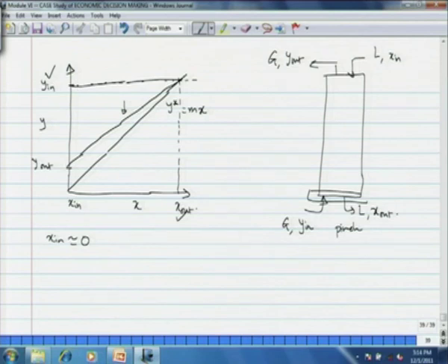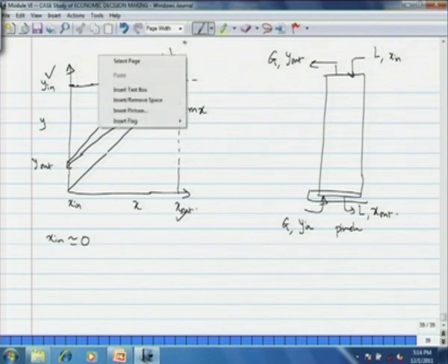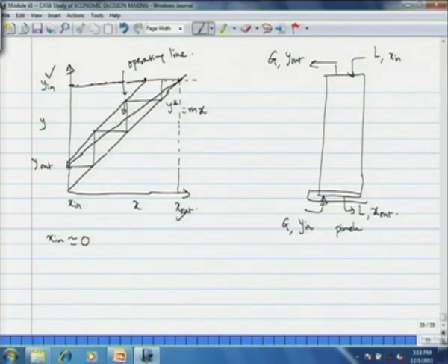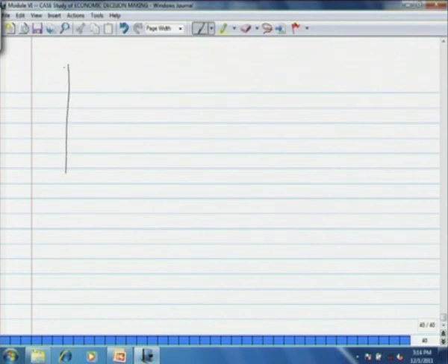You will always choose a liquid flow rate that is higher than the minimum, which gives the operating line, and then you would like to make out the number of plates or number of trays that are required for a particular operation. This is the procedure you have followed while determining the number of plates in the case of dilute and isothermal systems. However, in the case of a concentrated system, the equilibrium curve itself will be either parabolic or the reverse.